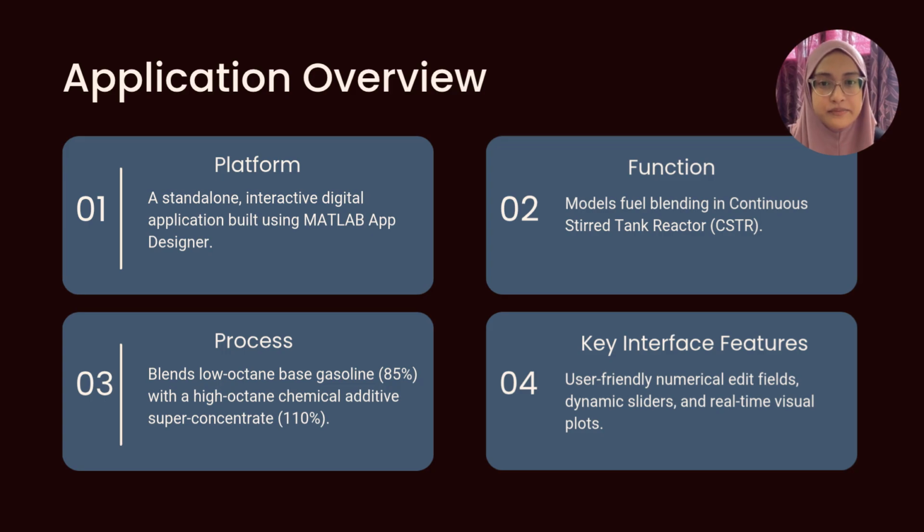What exactly is this analyzer? At its core, it is a robust computational engine wrapped in an interactive MATLAB graphical user interface. The app acts as a digital twin for a continuous stirred-tank reactor, known as CSTR, specifically modeling a fuel blending operation where base gasoline is mixed with a high-octane additive. Instead of relying on static steady-state algebraic equations, our application actively computes transient time-dependent behavior. The interface is designed to take the complex outputs generated by our numerical solvers and translate them into real-time visual curves and actionable data for an operator.